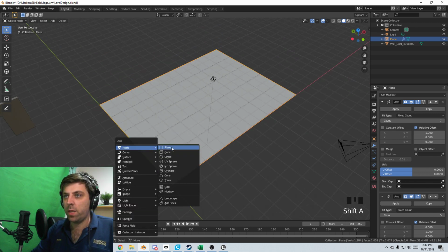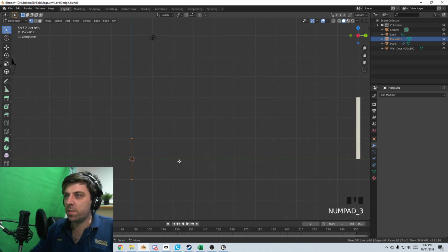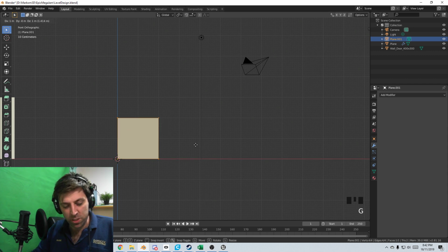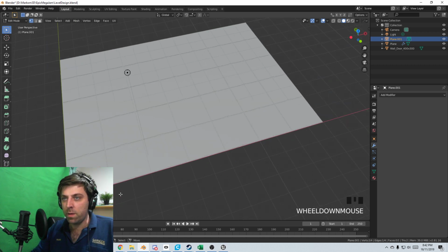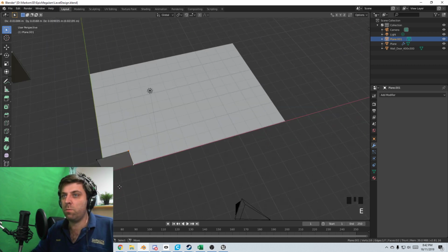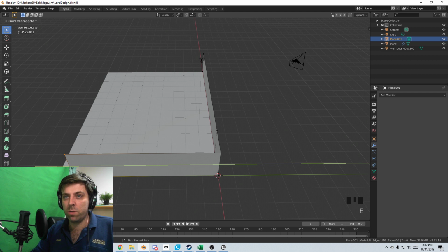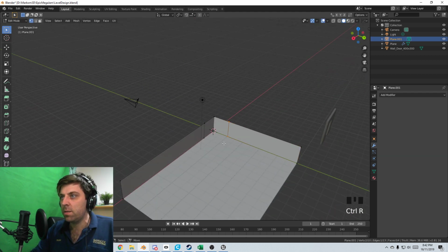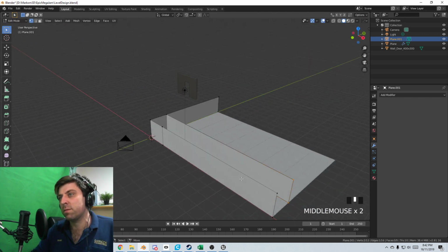And now let's just quickly block out the walls. Rotate X 90 degrees. I'm just going to use this as a placeholder for now. G X, and if I hold Control, it will snap to the grid. Let's extrude. What are we looking at? I'm doing everything in values of 2. Extrude X. Oops, sorry, Y. Hold Control so it snaps to the grid. From here, let's hold Control there. E to extrude X. Bring that over.